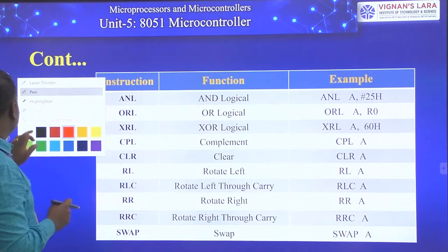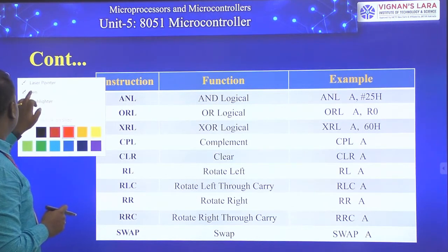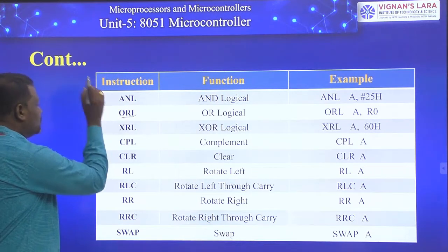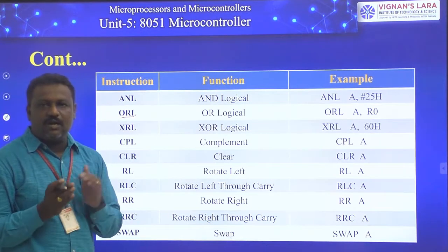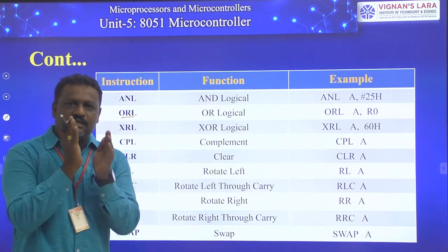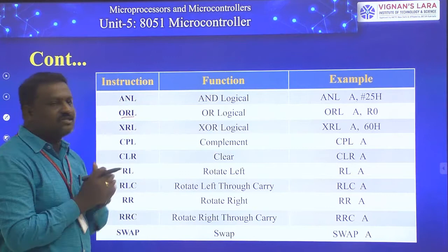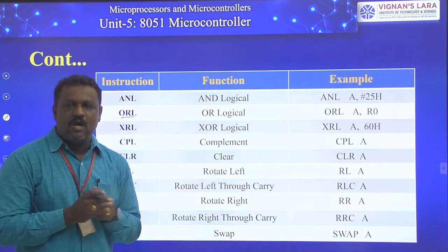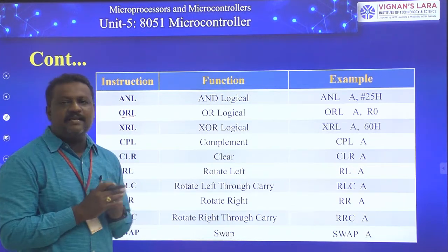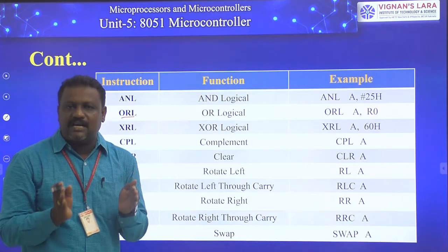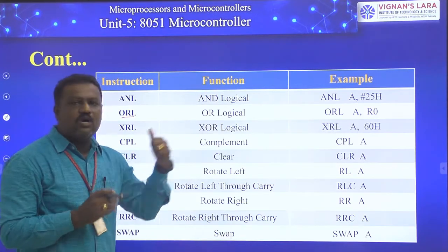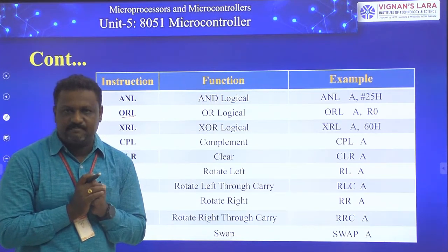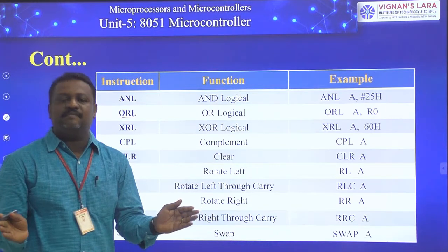Next, coming to my second instruction, that is ORL. ORL means OR logical. Here also, the conditions we know for the ANL instruction are applied for the ORL instruction. The only difference is that by using ANL we do bit by bit logical AND between the operands, but by using ORL we do logical OR bit by bit between the operands. Apart from that, everything is the same as the ANL instruction.